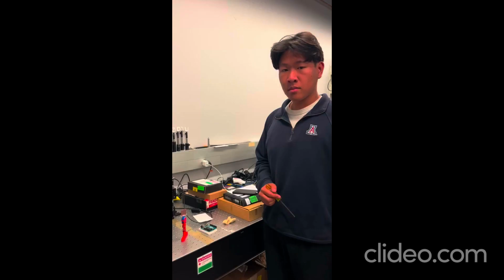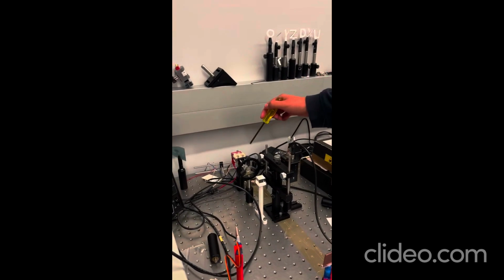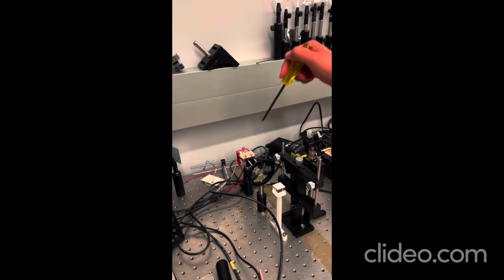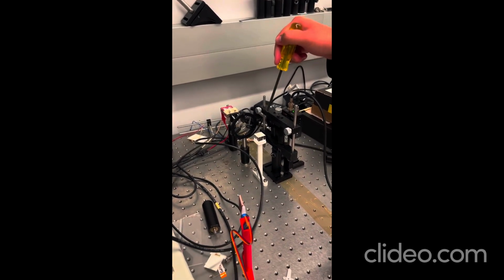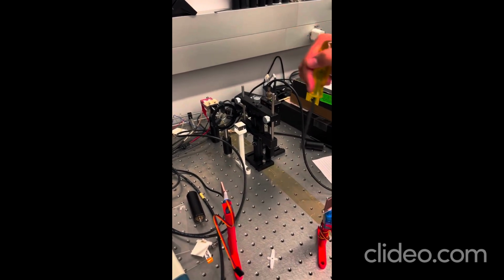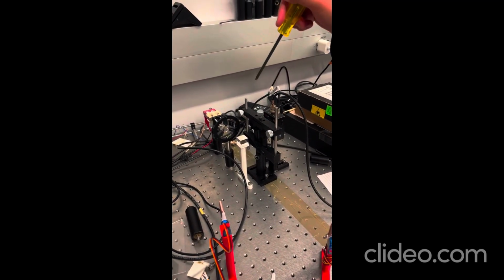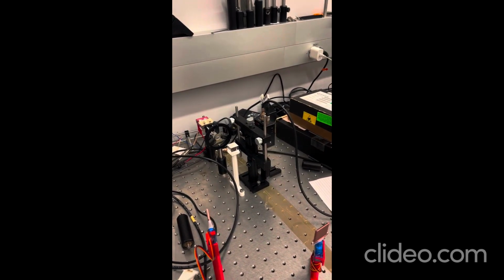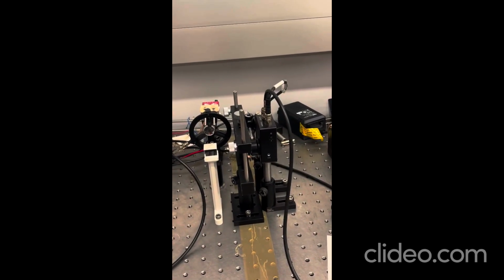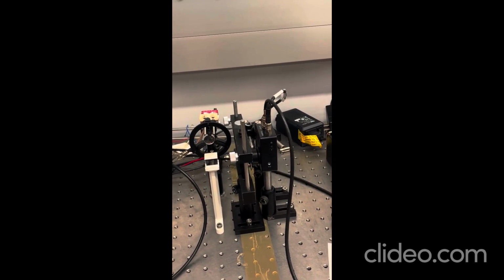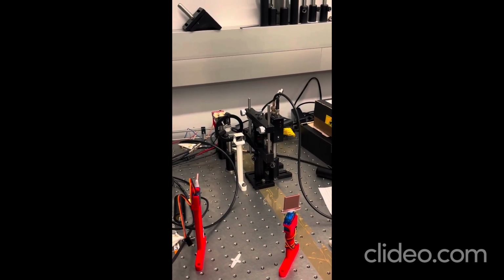So next, here's our optical setup, where we're using a 905 IR laser followed by a 55mm focal length lens to collimate the light into the beam splitter, where the light is then split and it hits the mirror, and the light reflects back into the beam splitter where the light is recollected and is sent into the APD, which is a 400 to 1000 nanometer wavelength photodetector, which in front has 2 ND filters to prevent oversaturation and a pinhole to filter out external light.